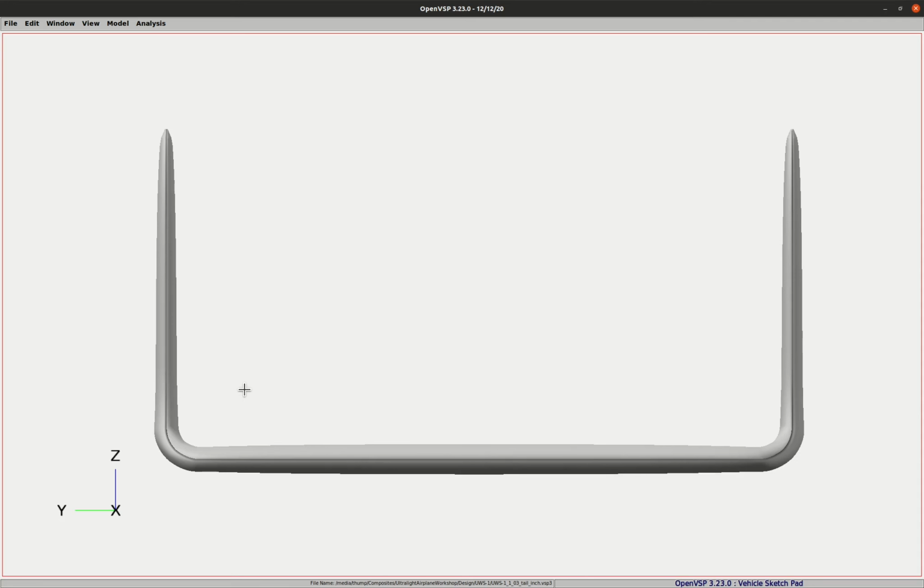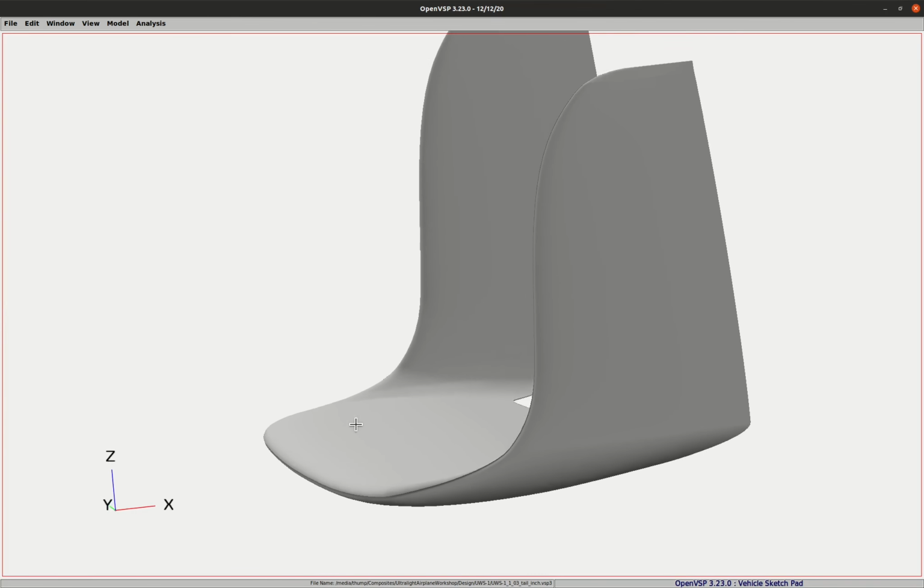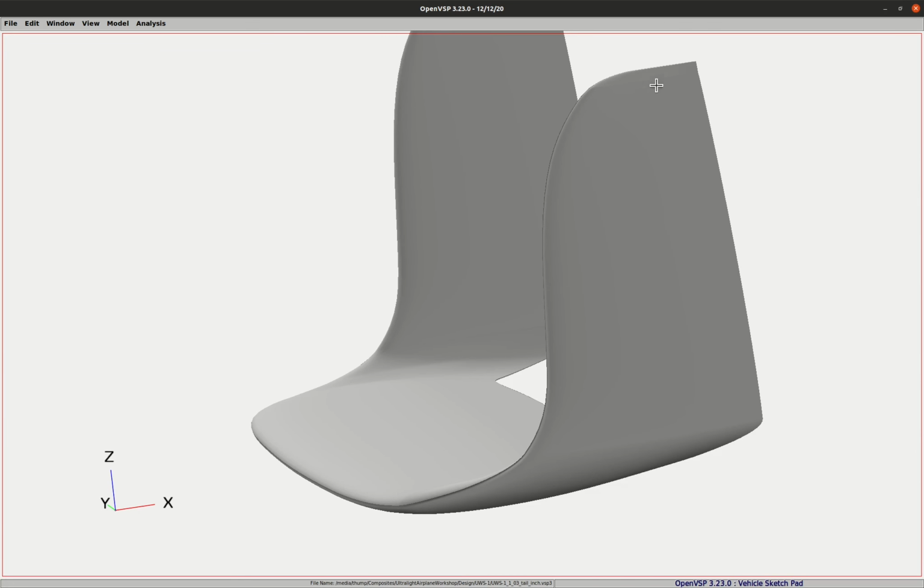Now let's take a view from the left. So again, here's the horizontal tail. I'll turn it like this a little bit so you can see the horizontal tail here, and here's the vertical tails. And here you can see an example of what we were talking about when we were talking about mounting a wing to a body. So I've shifted the rudders, the vertical tails, about 50% aft of the horizontal tail. So the thickest part of this horizontal tail is going to be close to the leading edge of this vertical tail, and vice versa. The thickest part of this vertical tail is close to the trailing edge of our horizontal tail. So we should get significantly reduced interference drag by shifting this vertical tail backwards.